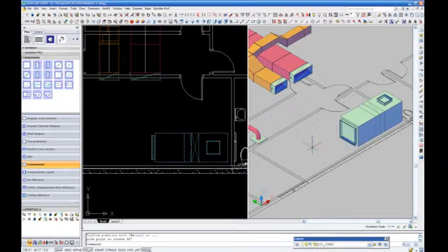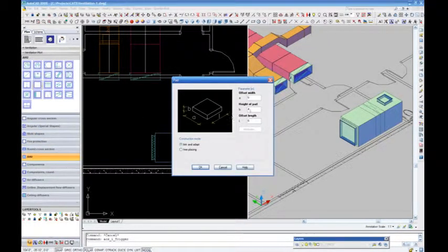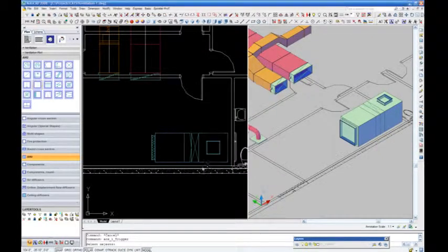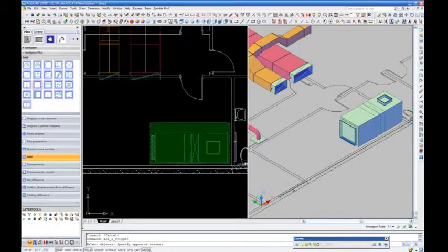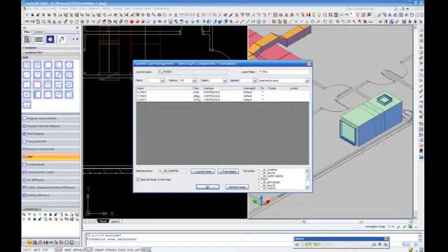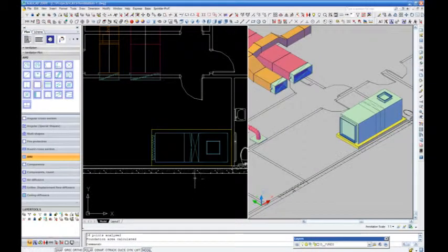Upon completion of the air handling unit design, we will design a housekeeping pad to be placed below the unit. Here we are giving a height of 6 inches, dimensions in A and B selection are selected at 6 inches. This will add 6 inches in all directions away from the air handler. Select OK. We will highlight our unit where the pad is to be placed. After selecting the layer, the unit will be raised up 6 inches automatically, providing the space for the pad.